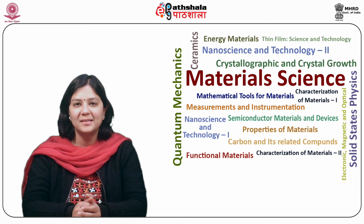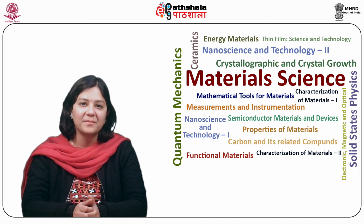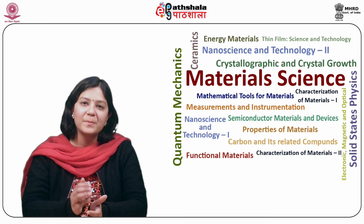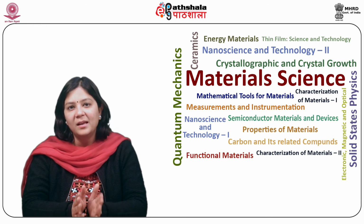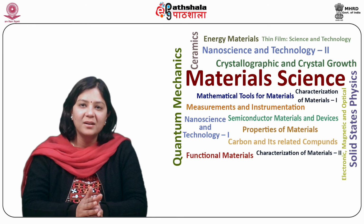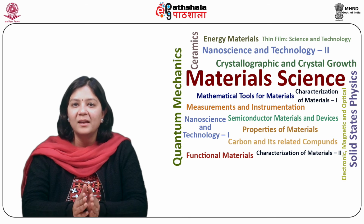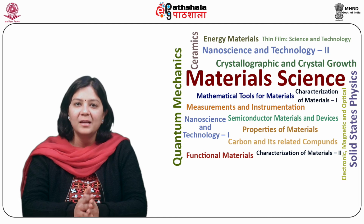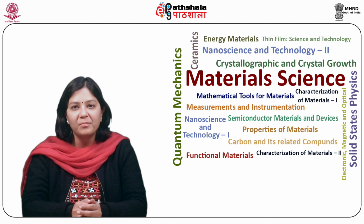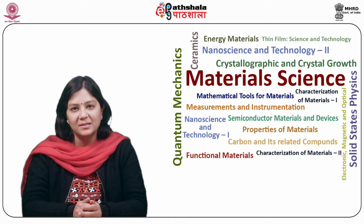A computerized data file is used to create the image of the mask. The computerized file can be produced by L-Edit, Layout Editor, Clewin, etc. software. This data file is converted into a series of polygons, which are then written on a square-shaped fused quartz substrate covered with a layer of chromium used in the photolithographic process.